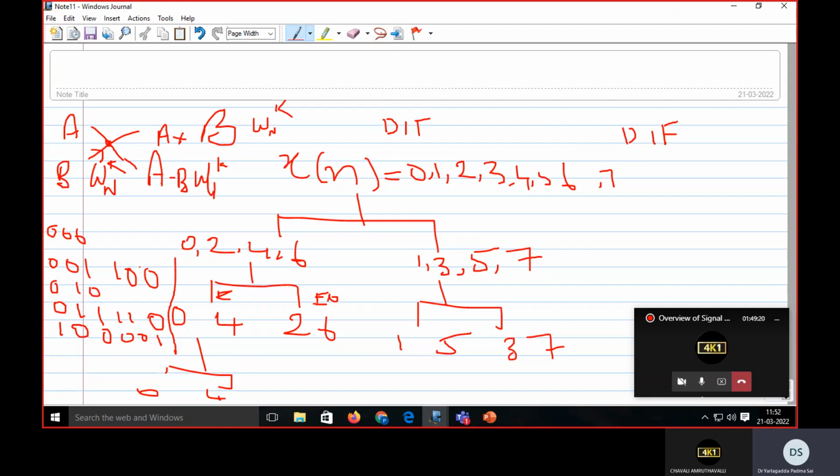If you use one bit reversal and one natural order, you require 2n memory locations. When you design a chip, memory is very crucial. You are saving 2n memory locations, and as the memory is less, the cost of the chip becomes less. So all these points are very important. Solving the problem is very easy, but this is the concept.